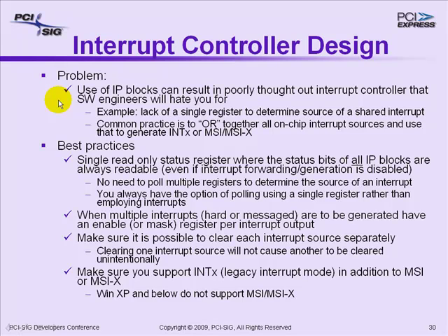A common practice is just to basically take them all and OR them together. The problem with this is that software has to then go looking around to figure out where the interrupt source came from. So best practice is to employ a single read-only status register.